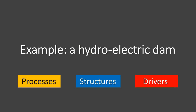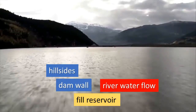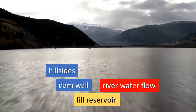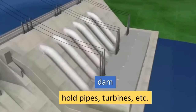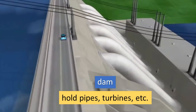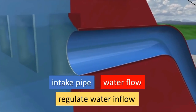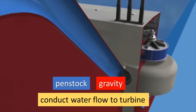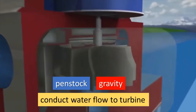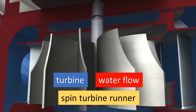Now, let's review this example in terms of processes, structures and drivers. The reservoir fills with water because the hillsides and the dam shape the river water flow. The dam structure holds the pipes, penstocks, turbines and generators in place. The intake pipes regulate the river water flow into the penstocks. Driven by gravity, the water flow is conducted by these penstocks into the turbines. Inside the turbine, the massive water flow spins the runner.